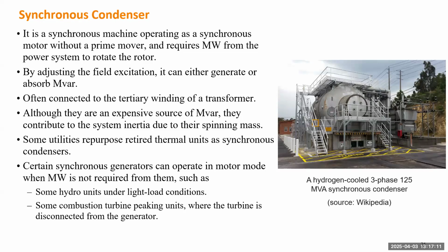Okay. And when you have more and more renewables in the system, you need to have spinning reserve. Remember the duck chart we talked about. If the solar needs to drop within 1 or 2 hours quickly, you need to have some generation to pick up. So it's better that those generators are just spinning there, and they can easily increase their output by the load frequency control. So such units, if they're not providing any power but are running there, can be utilized as synchronous condensers.